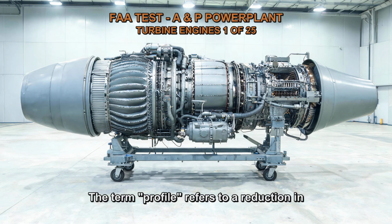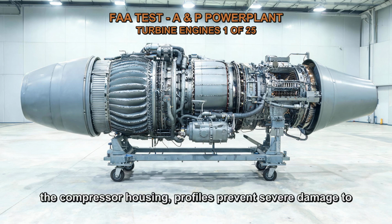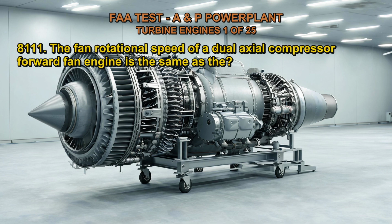The term profile refers to a reduction in the thickness of the blade tip of a turbine engine compressor rotor blade. If the blade should come into contact with the compressor housing, profiles prevent severe damage to the blade or housing.